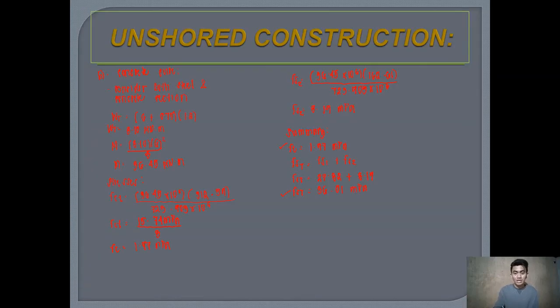So this is way below FC allowable, and then this also does not exceed Fs allowable, which means that the stresses are also adequate under unshored construction.